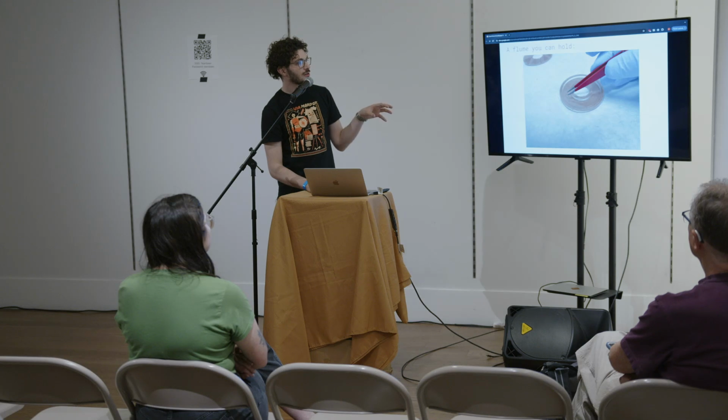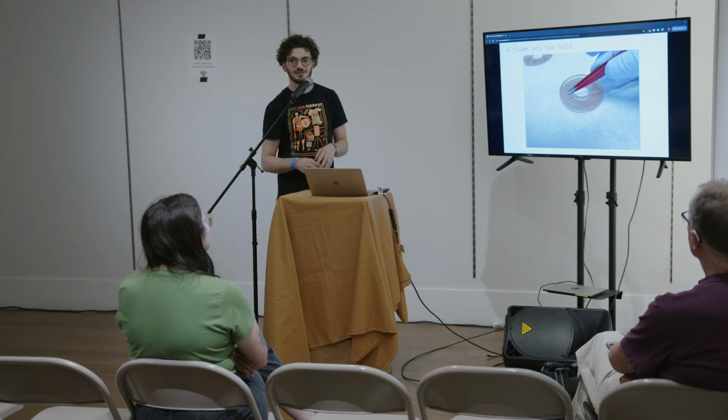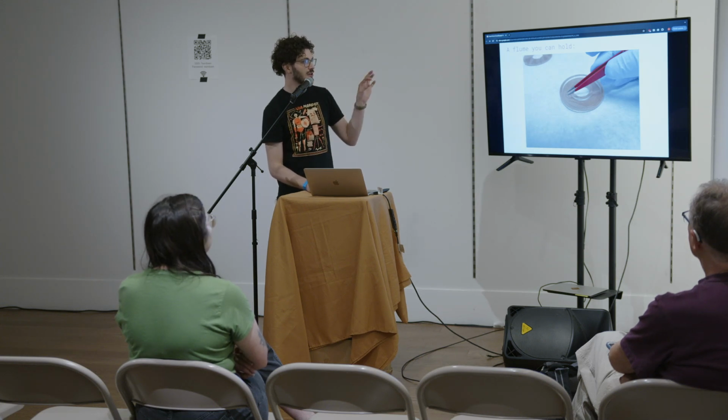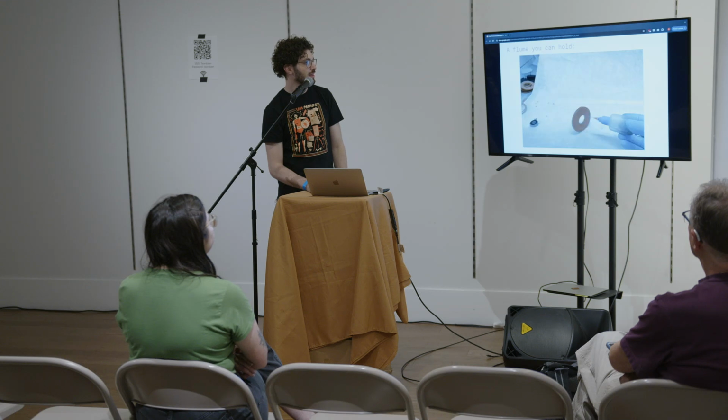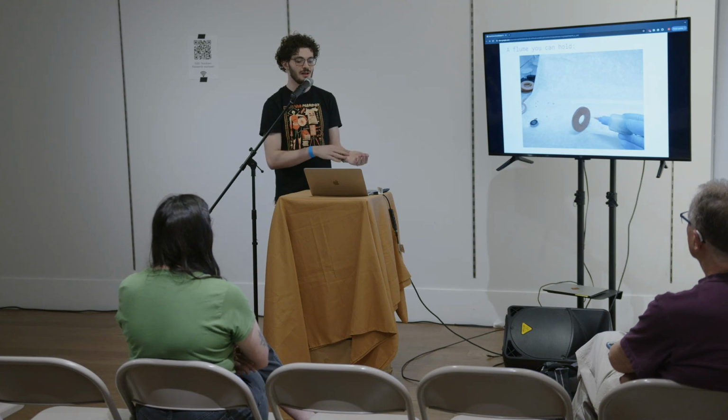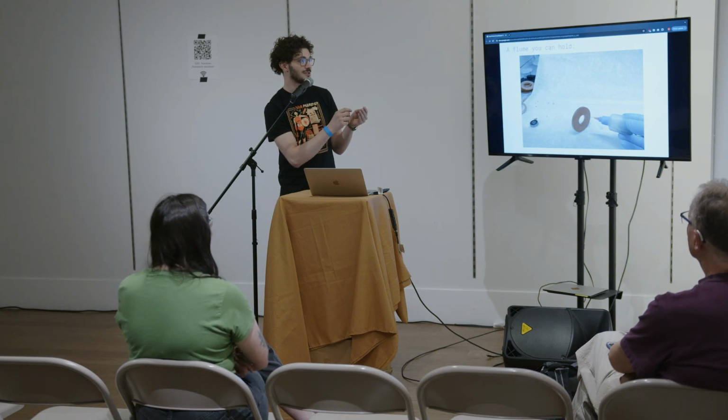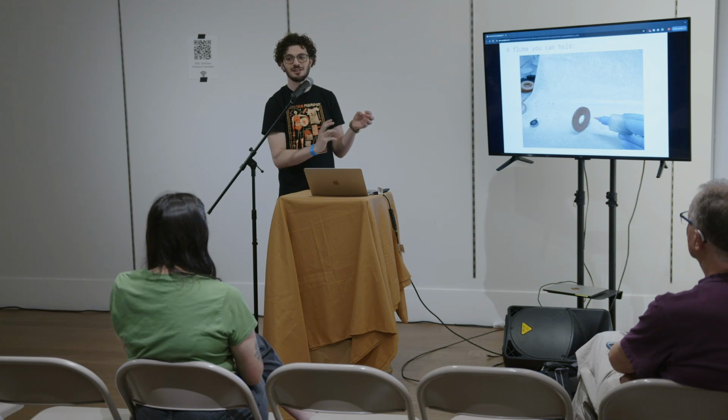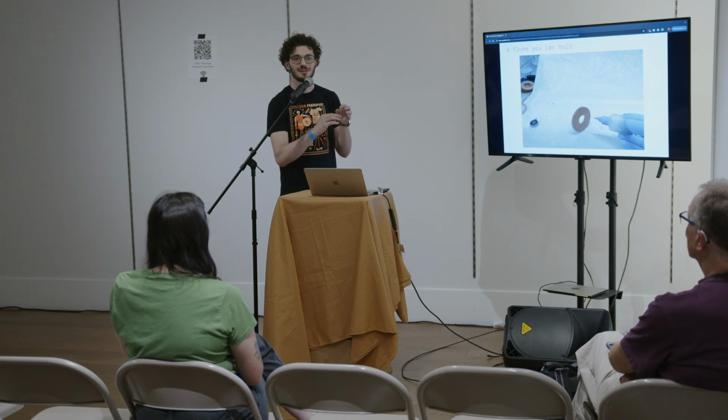So we do the inner and outer rings, aligning them visually, and then add this cylinder that gives you the flow past the cylinder visualization for this specific toy. Again, it's just a tiny drop of solvent and then placing the cylinder in place. One thing that I found useful, after I flood the rings on the top and add the top layer, was adding a little bit of solvent into the whole body of it and then just shaking it around everywhere. That seemed to smooth things out. I don't know, the vapor from the solvent maybe dissolves all of the edges just enough to make it more reliably watertight.